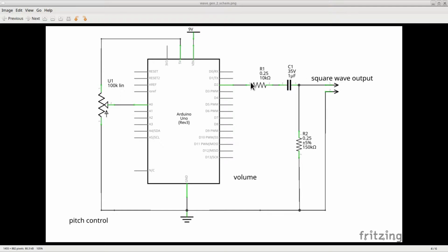Resistor R1 is there just to limit the current that can be drawn from the Arduino pin. We don't want to burn the circuitry on such pin, trying to extract a current beyond its capabilities.